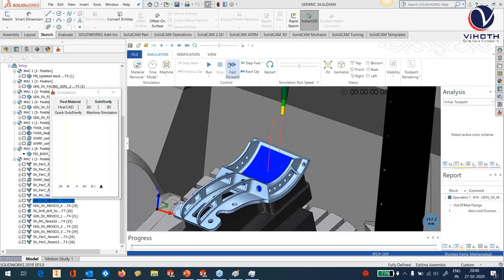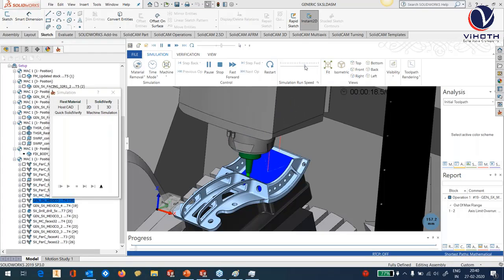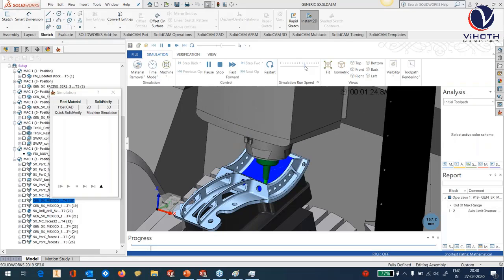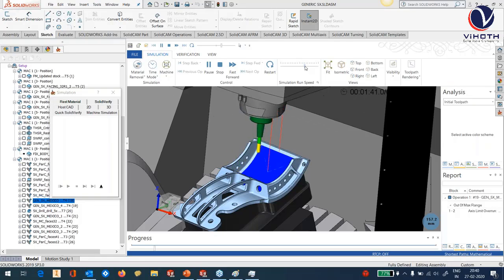Okay, one of the ways you can solve many of your problems is to use the common direction. It's a relatively underutilized functionality in SolidCAM. You can see that it's completely 3-axis now. Complete collision-free 3-axis machining. You don't need to define or make any 5-axis toolpaths. It's a very powerful 3+2 functionality available inside the simultaneous 5-axis engine.